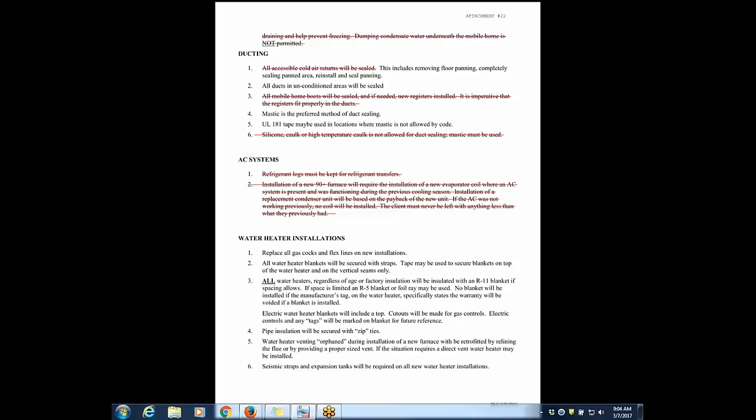I just want to ask, on number 3 on the water heater, is everything on there still valid? Yeah, I'm going to say yes. You should always try to insulate a water heater. There's always heat transfer taking place there, and insulate it with whatever you can get on it. I understand, and I totally get it. You can't always get an R11 or R13 blanket on. Sometimes all you can get on is an R5. Because of the temperature difference there, anything you can do helps. So that's where I'm at with it. Some of that is covered in the water heater safety checklist also.